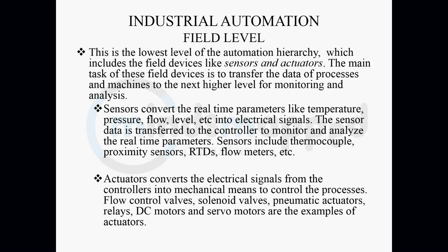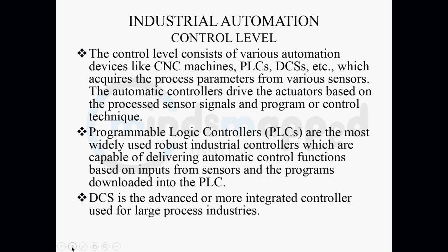That means the actuator will move to close the valve. While if it was falling below the acceptable range, it will open the steam inlet valve to let more steam come in and let that water be heated more to the temperature where it is in acceptable ranges, right? Yes, sir. Yes.